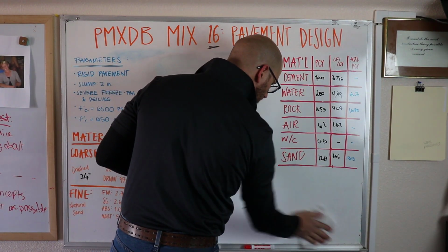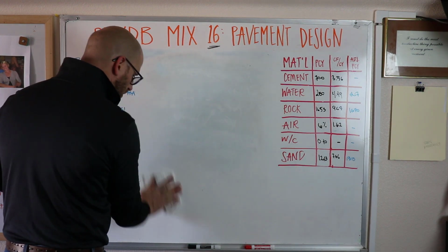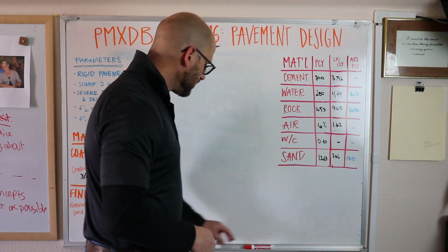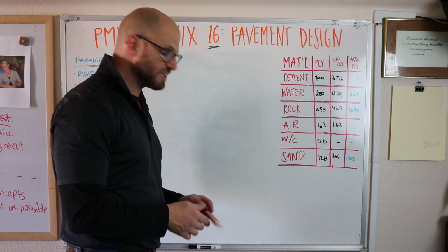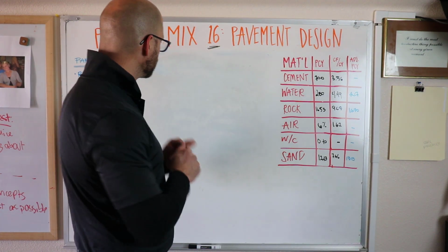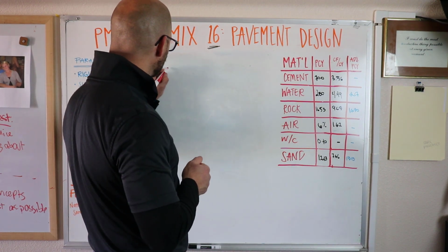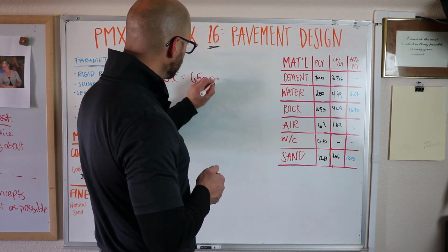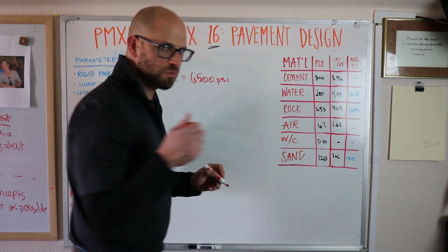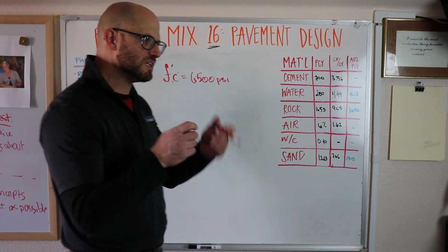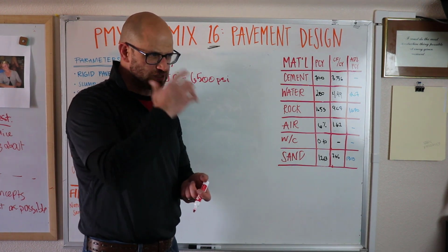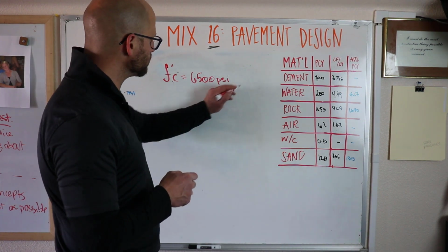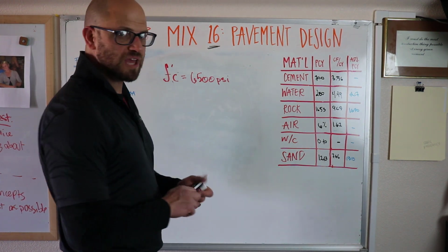We adjusted the waters. You know, the thing that we have to come back to is we need to be cognizant of our engineering properties that we need to go after. First and foremost, we had an original f'c of 6,500 PSI. But when we look at ACI 318, I believe the newest edition is 2017. Anyway, there's a plus 1,200 PSI that we have to take into account.